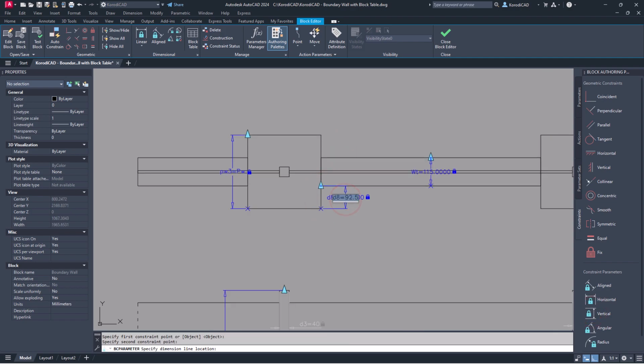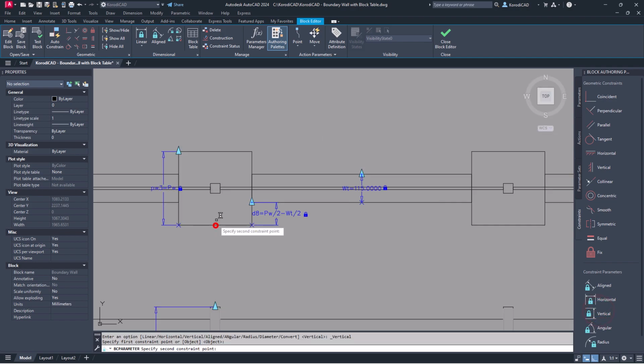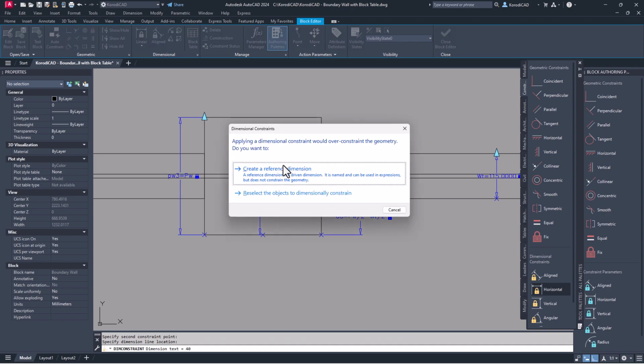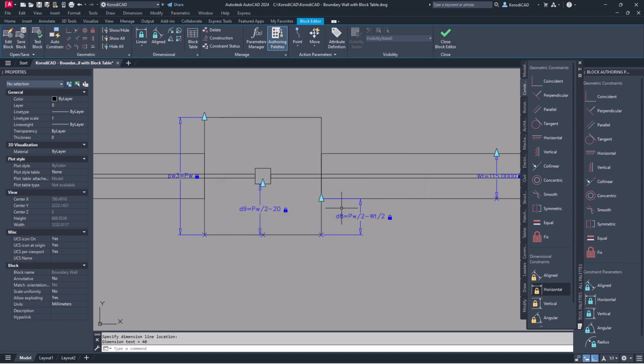Specify a mathematical operation for the vertical parameter, so that the wall is always on the axis of the post. Do the same with the fence post. Fix the dimensions of the fence post. If you try to enter a value that is already fixed, you will be warned that it is not necessary. So here you only need to fix a vertical value.